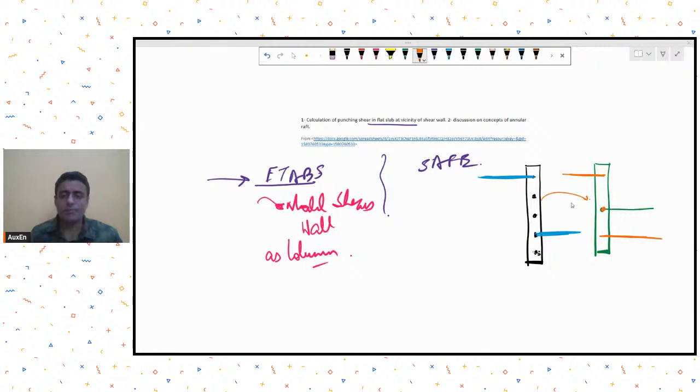That is the problem. You understand? So in such a case, maybe you can use the concept of rigid links and model rigid links over here, which will help you to get over this issue. So this is one of the ways, although not a very convenient way of doing it, but you may do it this way. What can be the other way?